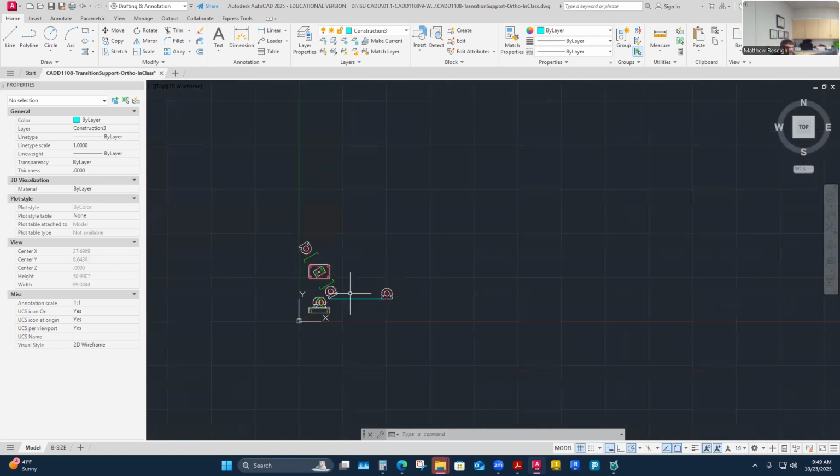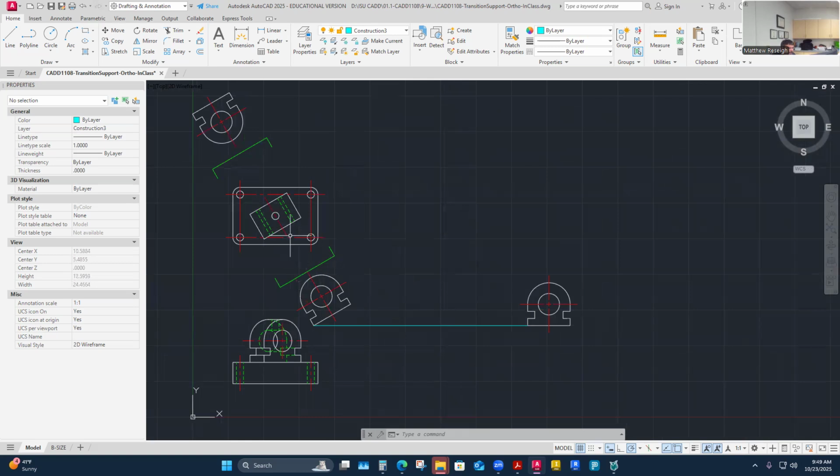So that'll make sense to someone that says, "Oh, I'm looking this way," but that wouldn't be totally an orthographic alignment. It would really look like this. So if I'm seeing the view that's been removed from its orthographic alignment, I just add some more detailed notes to it. Even if I had to scale it up and make it bigger, I would add that information to my view as well. My view AA has been rotated 30 degrees and scaled to 2 to 1, so I can dimension it and detail it a little finer.